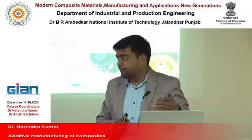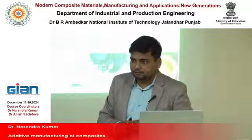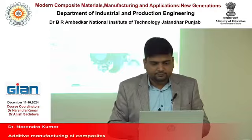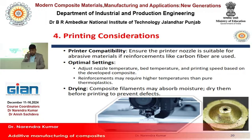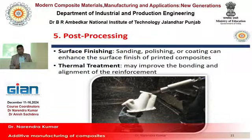So suddenly the property of the matrix may change due to the addition of the reinforcement. This is a very important thing that you need to consider. And drying is also very important, because composite filaments sometimes may absorb moisture. So ensure you dry them before printing to prevent any defect. And sometimes you need to do post processing, surface finishing, right? Thermal treatment sometimes may be required.